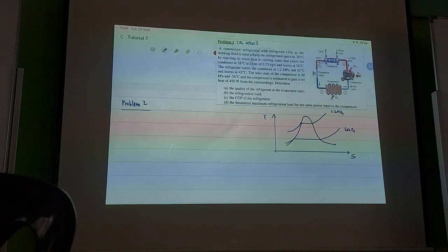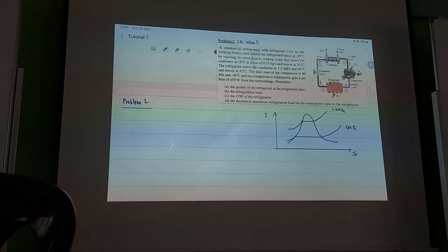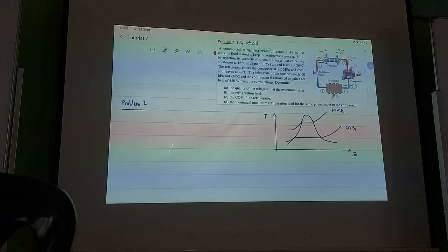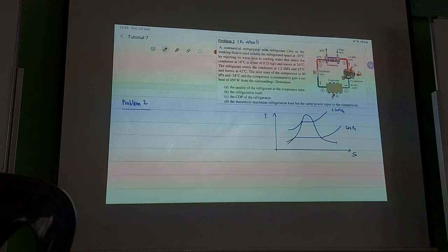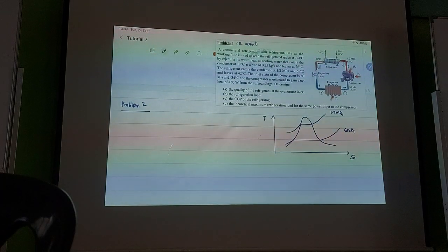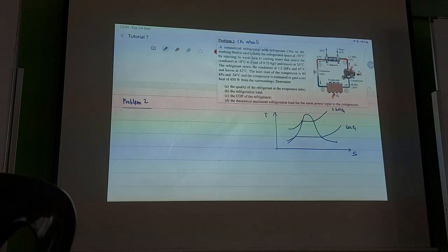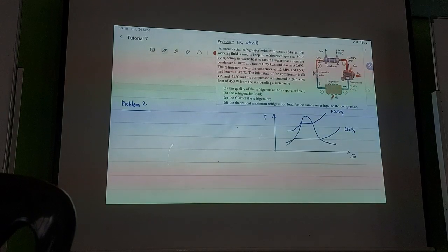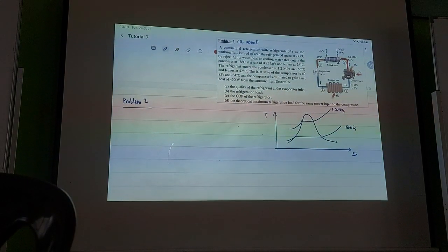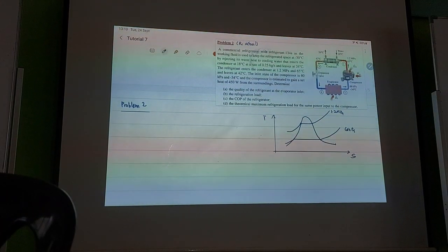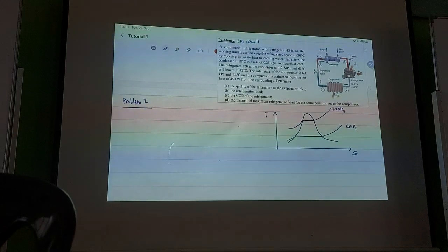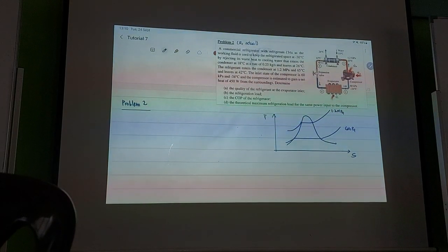Now, based on the information there, if you look at state 1 and state 3 and go through the tables, you will see that these are at a superheated state as well as a compressed liquid state. This question didn't really ask you to draw, so that's fine. I'm just drawing this to show how the thing goes. So maybe I write down the information first. It enters the condenser at, oh, that's the water. So this one we don't care about first.